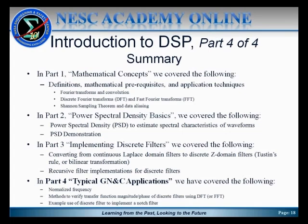First of all, we started that discussion by discussing Laplace transforms and Z transforms and how those can be related using Tustin's rule of the bilinear transformation to transform from the S operator of the Laplace domain to the Z operator of the Z domain. And that's key to converting continuous domain filters into discrete filters. We also showed how you can build a recursive filter that actually implements those discrete filters, which we've then used in this part in an example that we just covered.